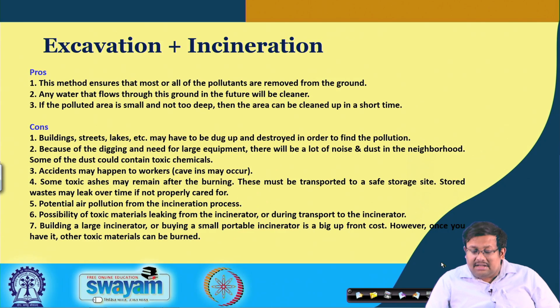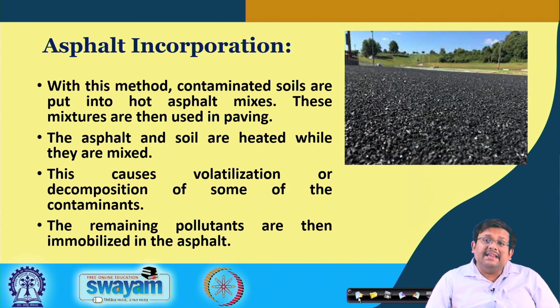So, we have finished this excavation and incineration. And the next method of ex situ decontamination is asphalt incorporation. Now, with this method, contaminated soils are put into hot asphalt mixes, and these mixtures are used basically in paving, as you can see in this picture. The asphalt and the soil are heated while they are mixed, and this causes volatilization or decomposition of some of the contaminants, and the remaining pollutants are then immobilized